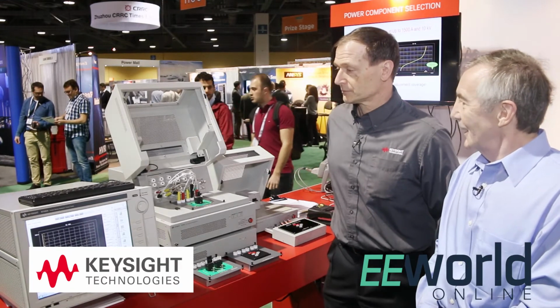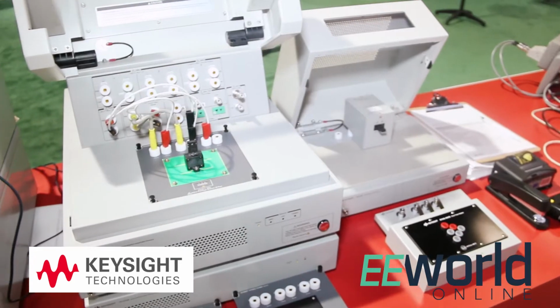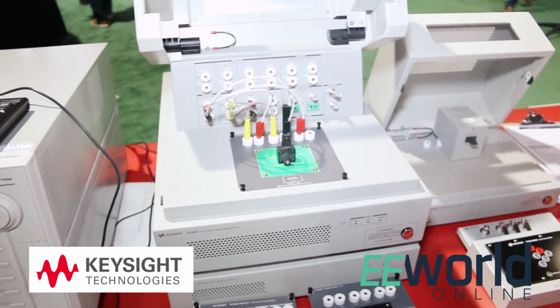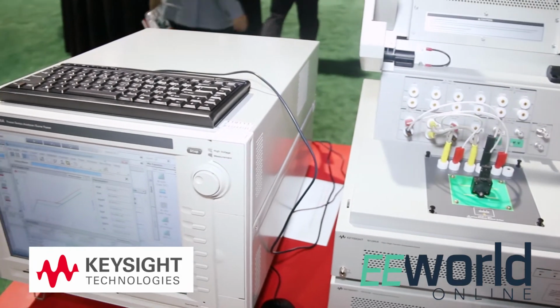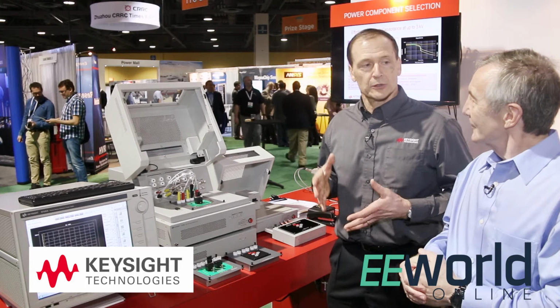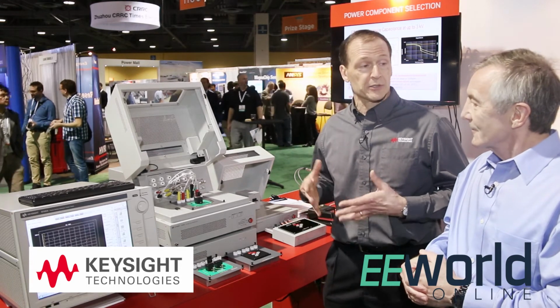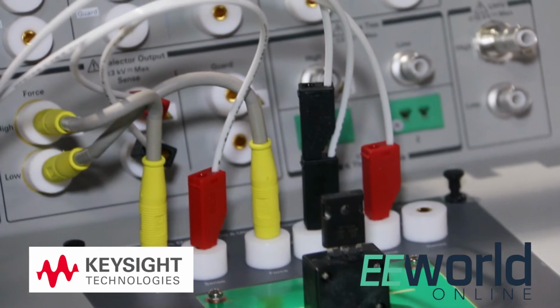Right. And at this show, there's a lot of talk about the wide bandgap devices. How does this thing behave with those? Yeah, that's a good question. Well, of course, a lot of what you do with wide bandgap is being able to measure, for example, things like low on resistance, which we can do. We can even measure sub-milliohm on resistance at hundreds of amps of current.